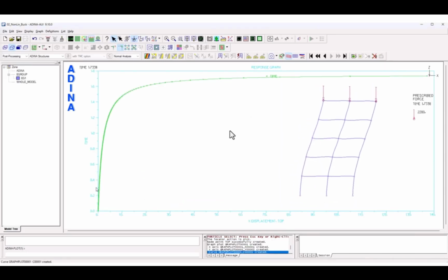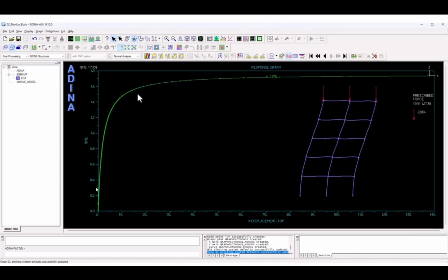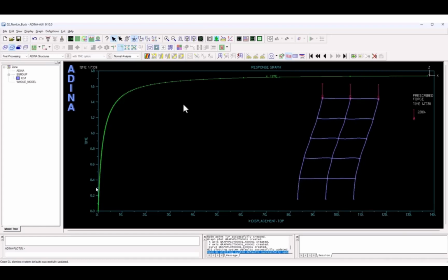And we see how we never reach the 1.766. What happens is the structure starts to drop its stiffness drastically as we get closer to the buckling load factor, which is exactly the equilibrium path we expect for a structure that is suffering global buckling.